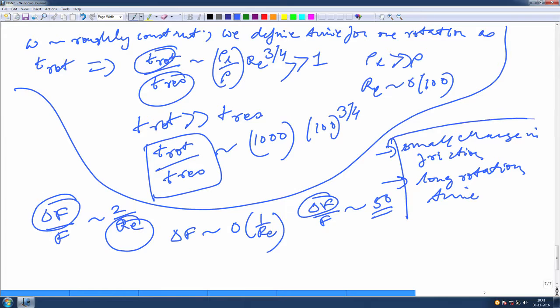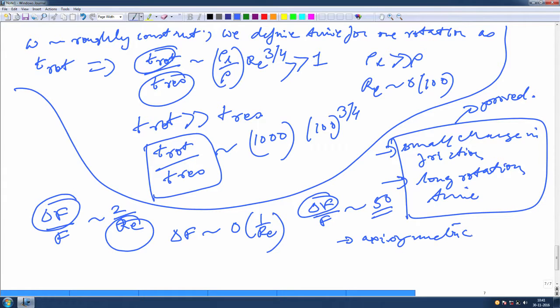So, we have proved through our scaling argument that that is true. The rotation or asymmetric circulation is not significant for droplets with large Reynolds number values. Okay. So, whatever we portrayed in that PPT, where we showed what the regimes within the droplet are, is still valid. We can take it to be nice and axisymmetric. Okay. So, that would be the first thing, and there is no rotational effect. So, we can safely do the problem as if the flow is axisymmetric and there are no rotational effects, got it.